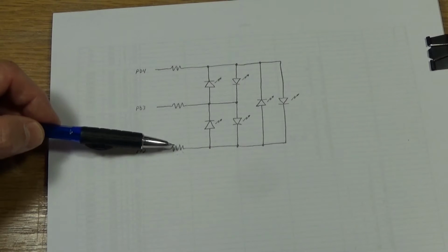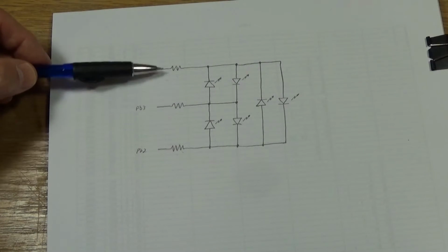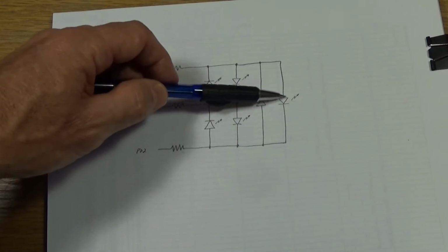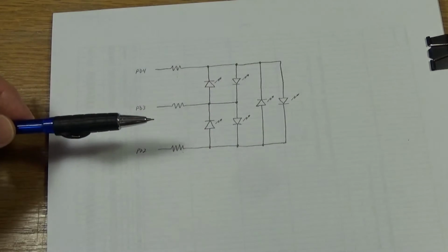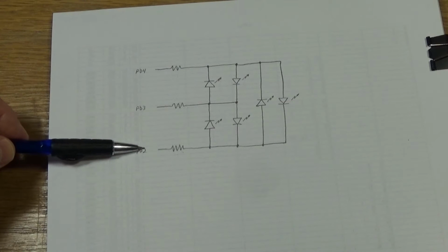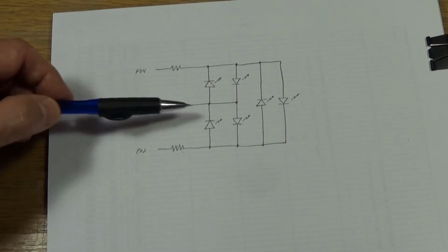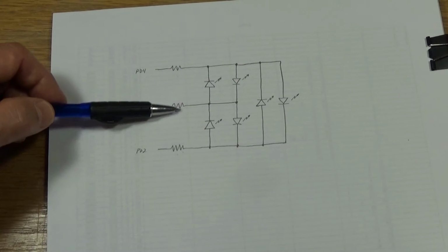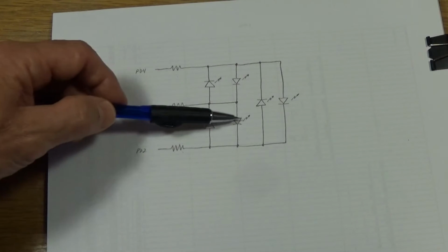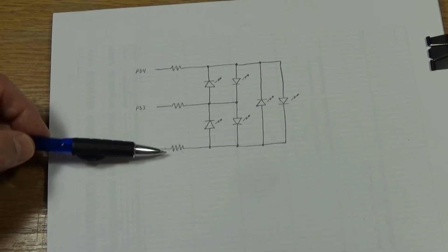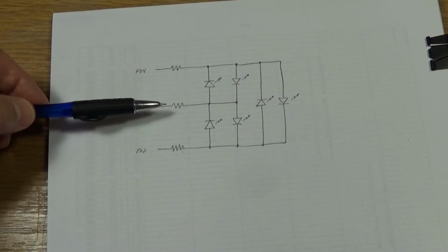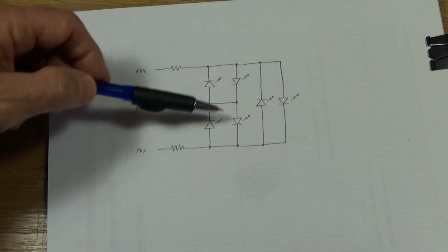And similarly with these two, or actually let's go back to these two again. With these two outputs, you don't want to have this one an output being driven low or high, because you're going to end up turning on one or the other of these LEDs as well. And so you make this one an input, so there won't be any current flowing in either direction into this pin. And then if you want to turn on these two LEDs, make these two outputs and this an input, and then you just drive the states of these two pins to make whatever LED you want go on and off. And the same with the outside pins would be outputs, and this one would be an input. And so that's how you can drive just one LED at a time.